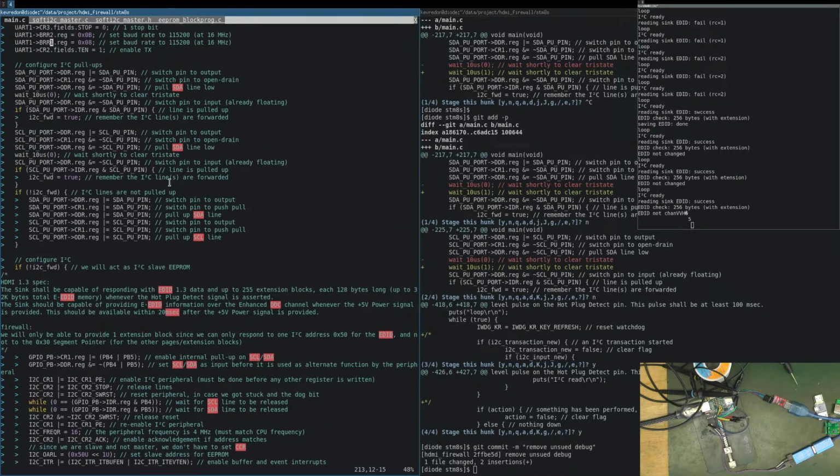So in the code, we will do that, configure I2C pull-up. And actually I will change and I will have more pull-ups. I will have 4, so 4 pins just to test the I2C pull-ups, just because I want them to be forwarded for HDCP to work. But luckily I have these 3 pins, so it's okay. It's not ideal, but it is okay. Although we see it worked with 1 kilohertz, it's just super slow, but it works. So do I really need to do it? Nah. I have spare pins, so I can do it. Should do it the proper way around.